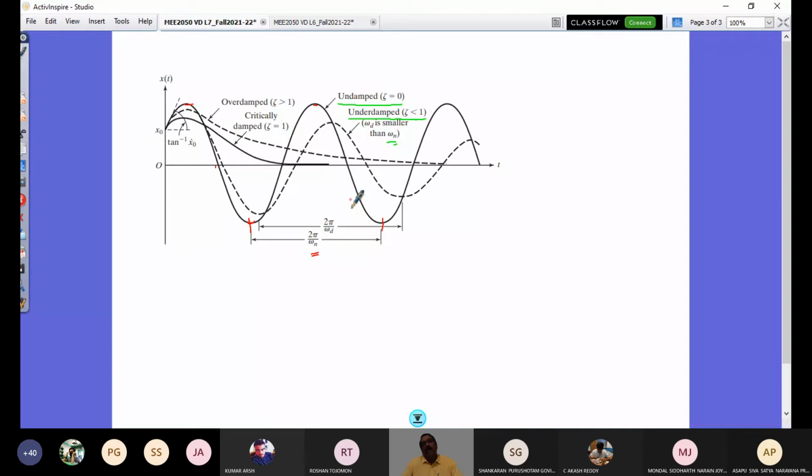And you see here, what is important is how the time period of the damped oscillation is defined. From any point x1 of t in the response, I go to the corresponding point after a cycle completion, and that is my second amplitude. This amplitude would be equal in the case of an undamped system, but here it is decaying. So this decay is what is going to help us define what is called the logarithmic decrement.